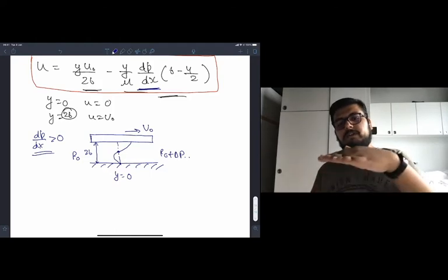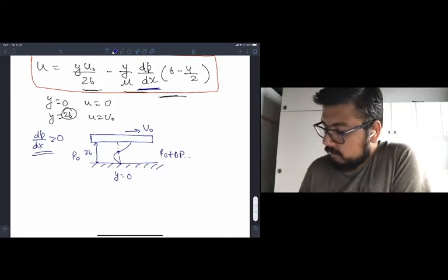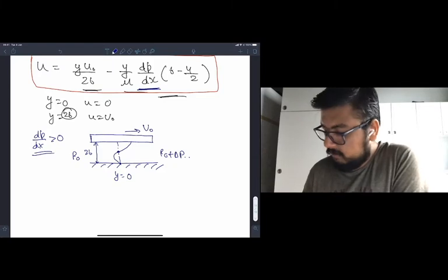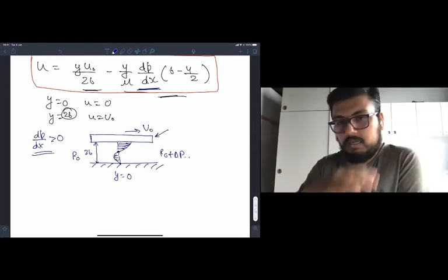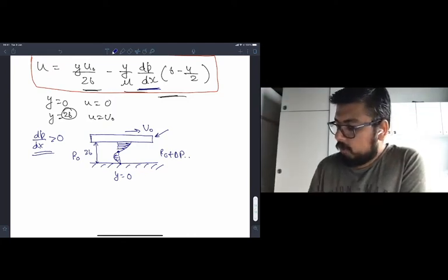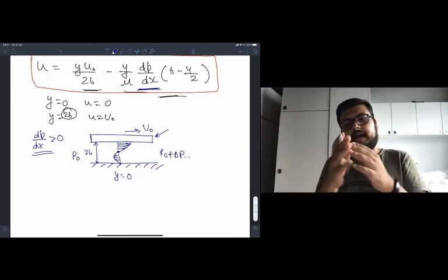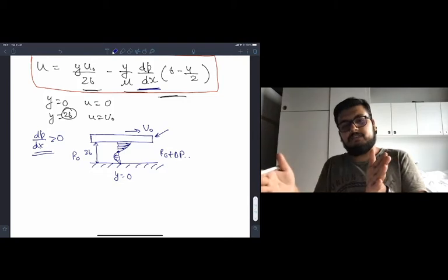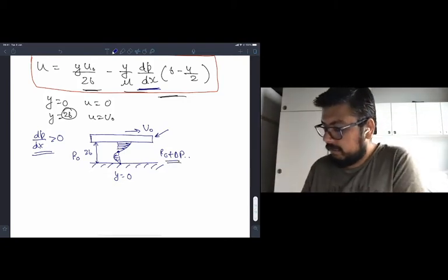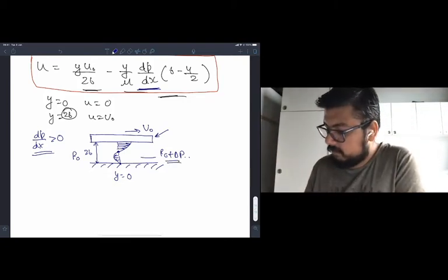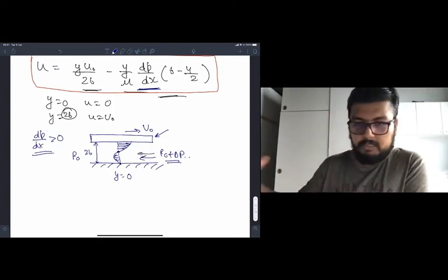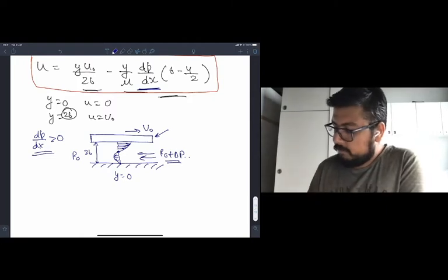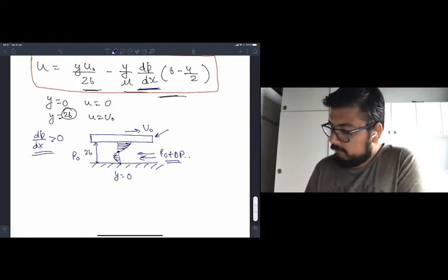Once at the wall where y is equal to 0, and then another point somewhere over there. And you can think about it physically as well. So the velocity is u naught at the plate at the top. However, you have a higher pressure as you go to the right of the domain. So you have a pressure gradient in this direction, which is forcing the fluid from right to left. Now, of course, this will win far from the top plate.